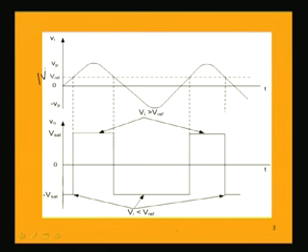Now, for the portion when the input voltage Vi is less than the reference, that means this portion from 0 to that point of 1 volt, we will get the difference voltage VID as V1 minus V2, where V1 is the signal voltage Vi and the reference voltage is 1 volt.